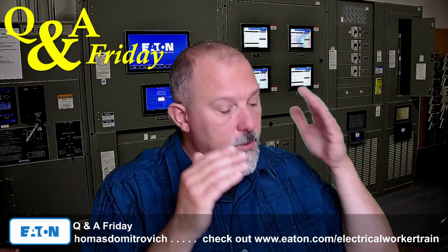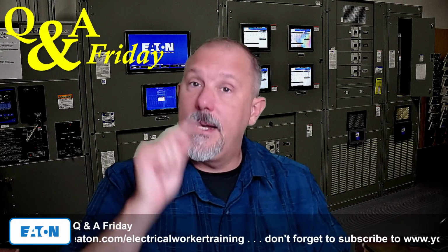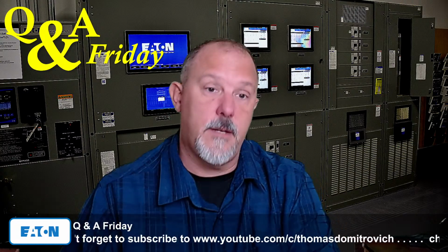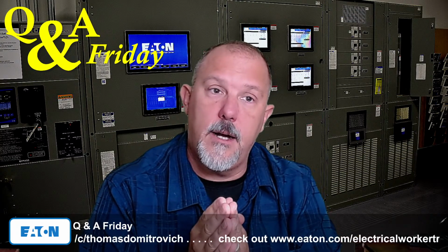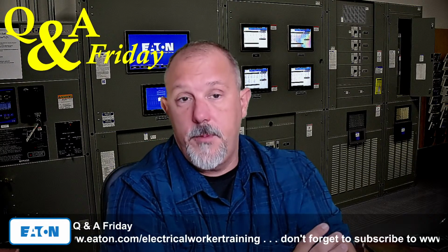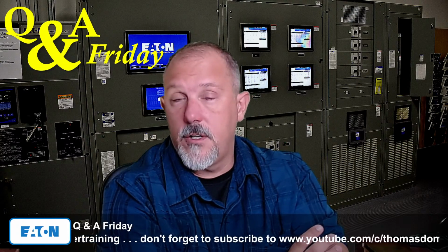Yeah, so remember 240.87 and 240.67 apply to any breaker or fuse, AC or DC, but not medium voltage, 1,000 volts and less, whether it's a service or a feeder, wherever it's at in the power distribution system. So the determination of when you need this requirement for arc flash reduction is driven off the size of the equipment. But I would agree, JW, that in reality, the size of the overcurrent device really doesn't matter.